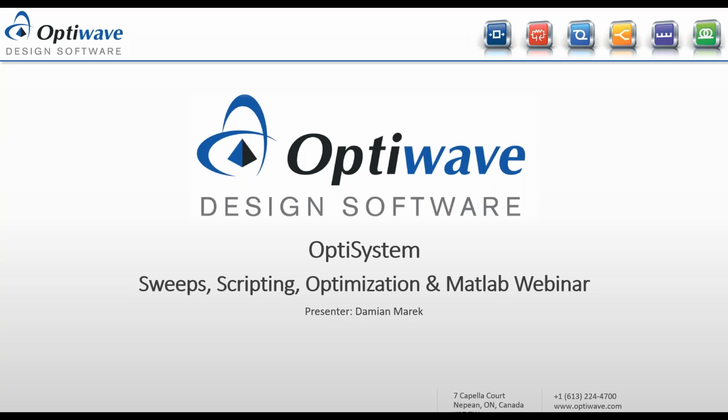And today we're going to be looking at some of the more advanced features of OptiSystem. So you've seen the sweeps before. I'll quickly touch on that. And then we'll look at scripting, using parameter scripting, using scripting as a layout tool, laying out the components using a script, doing some data exporting using the script.